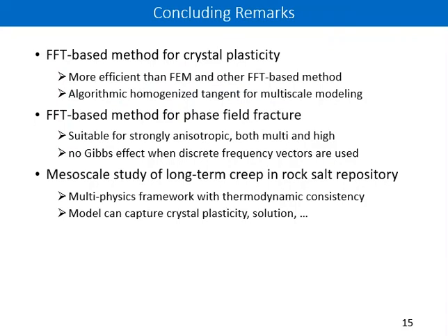We presented a multi-physics material model to describe the dislocation creep, the solution precipitation creep, the anisotropic fracture, and the crack healing process in polycrystalline rock salt with thermodynamic consistency. It is shown that our model is capable of predicting the long-term creep evolution within polycrystalline rock salt.